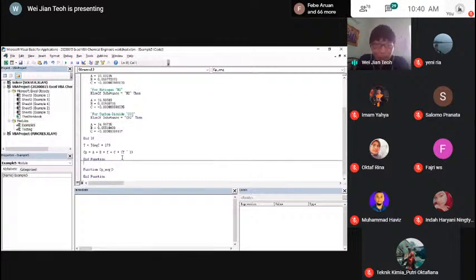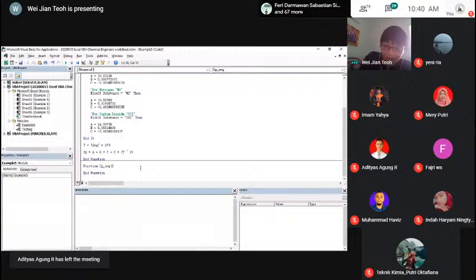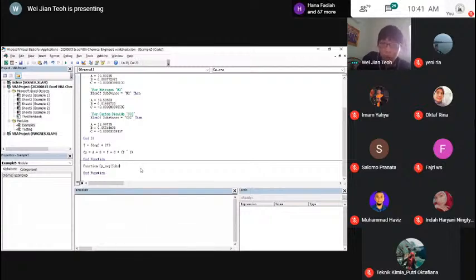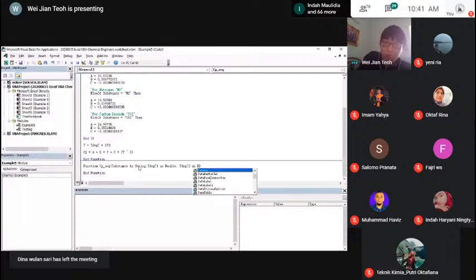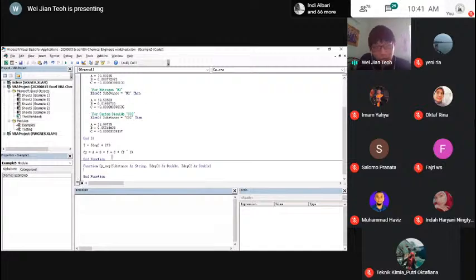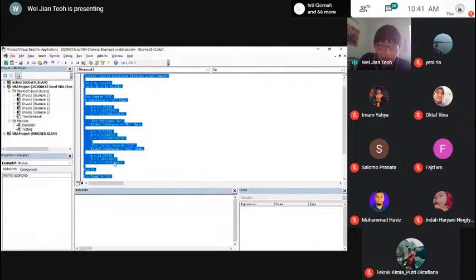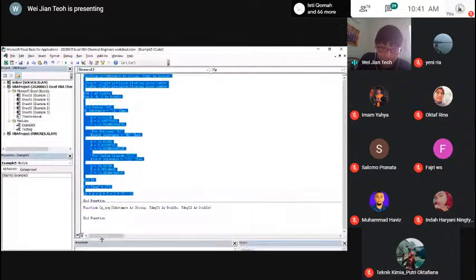So you can see that Excel actually adds a new line between these two different functions. And inside this function, I'm going to calculate the substance as string. Then we have temperature 1 as double, and we have temperature 2 as double. So what I can do now is copy this whole code again inside this new function.